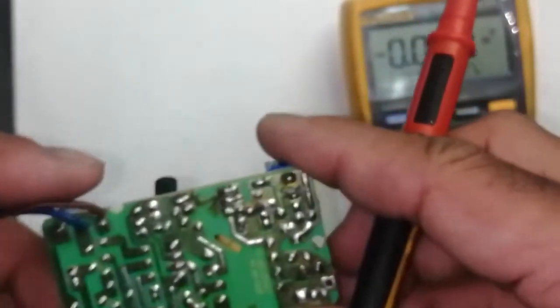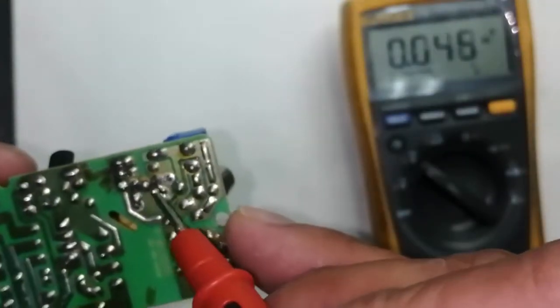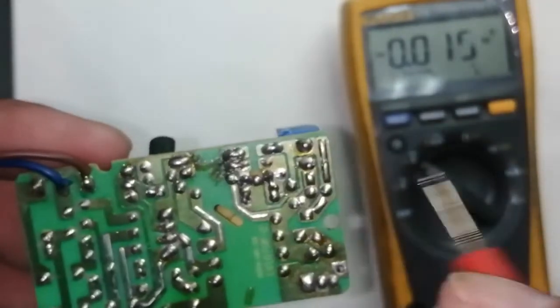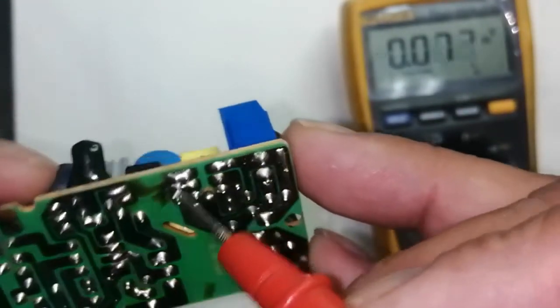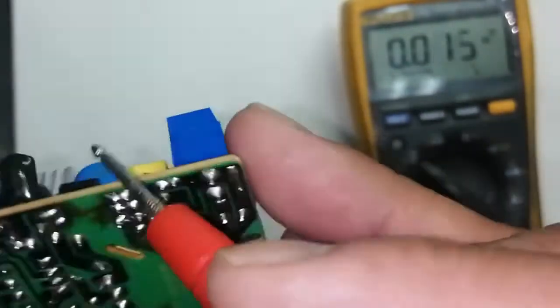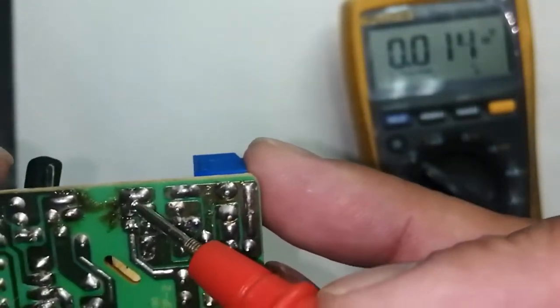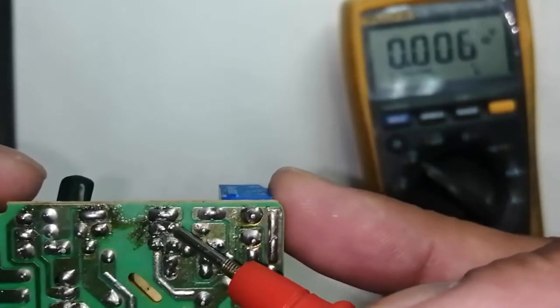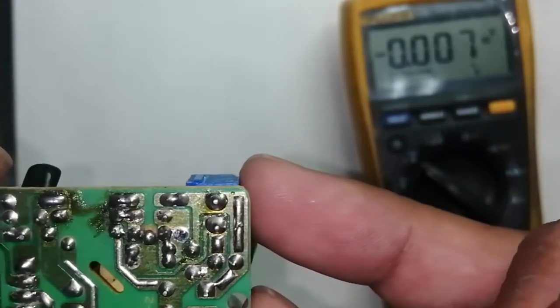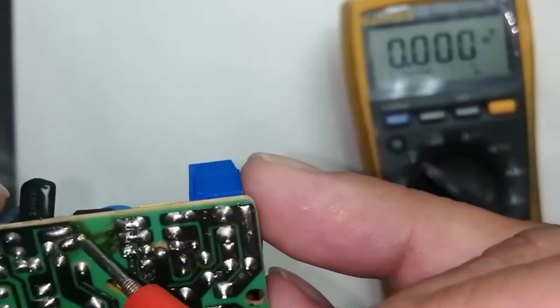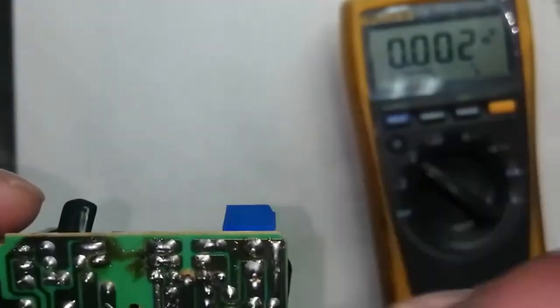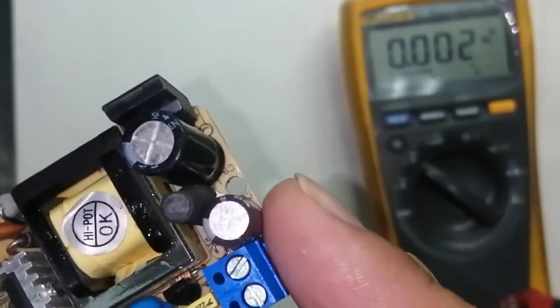How can we check? We have to check the center pin and the right, center pin and the left, DC voltage, and now at the opto isolator, pin number 1 and 2, we are measuring voltage. These are fluctuating voltages. Why? The fluctuation is due to regulation. The output pin is also changing voltage. Okay, we have a problem in this area now.